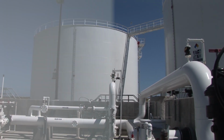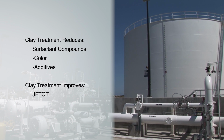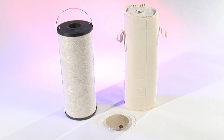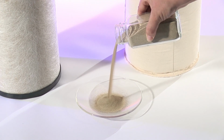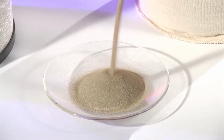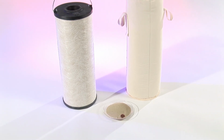Clay treatment removes the surfactant compounds, color, and additives and can be used to improve the JFTOT, Jet Fuel Thermal Oxidation Tester value. The key to the success of these treaters are the elements of highest grade attapulgite clay. This clay is like a very fine sand, with each granule having hundreds of tiny fiber-like crystals that capture molecular surfactants. Each pound of attapulgite clay has over 13 acres of surface area.